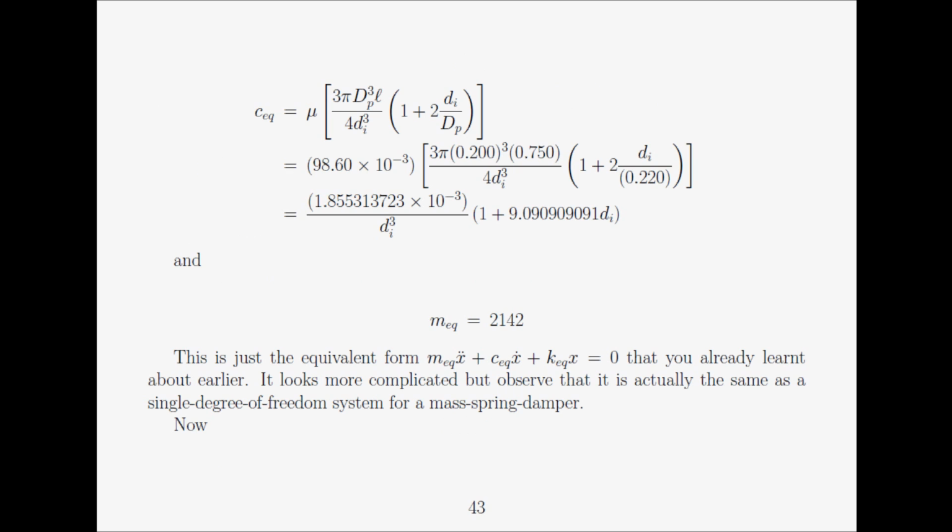If you have a car of about 1,000 or 1,400 kilograms, depending on the make and model, and you look at the suspension of the car, sure, the helical coils can be quite thick, but the mass of these coils is substantially smaller than the mass of the total car. In the same way, if you look at the shock absorber system, the tubes that go into each other, the mass of the shock absorber system is substantially smaller than the mass of the car or the motorbike or whatever the case is. So effectively, we just assume the equivalent mass is just the mass of the train.